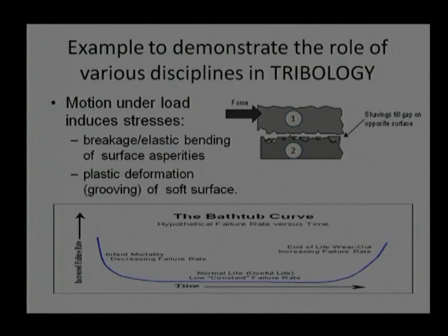Once the useful life of the component is over, the wear rate will increase again, and that will increase the clearance between components, the noise, and the vibration, and we need to replace that component.